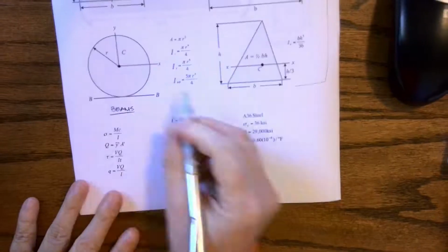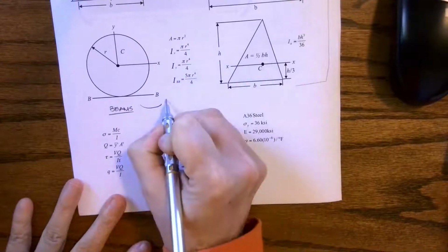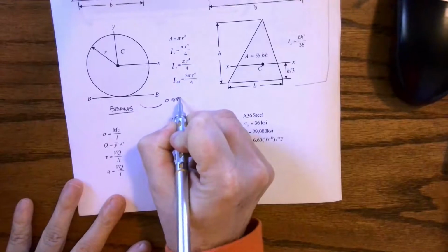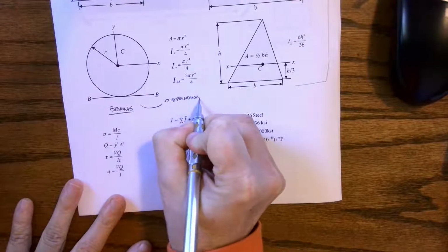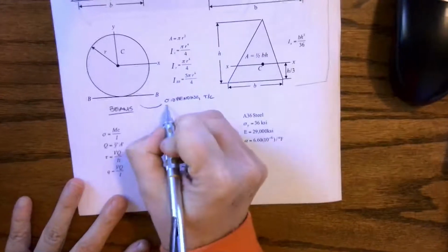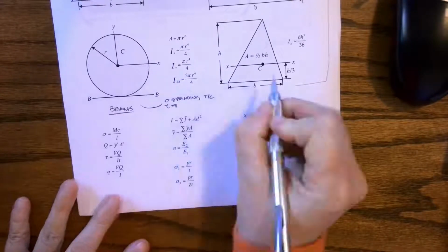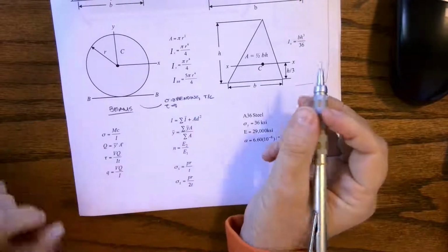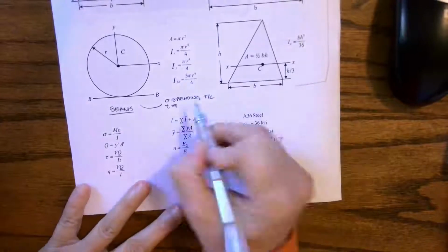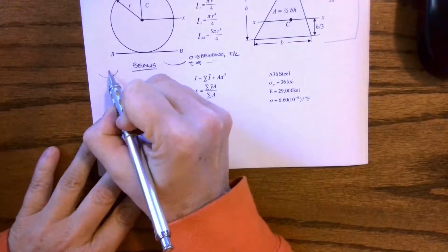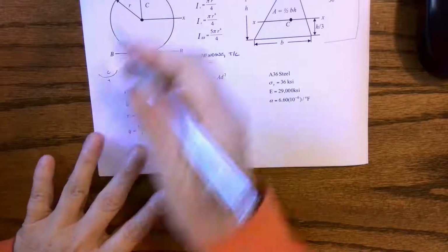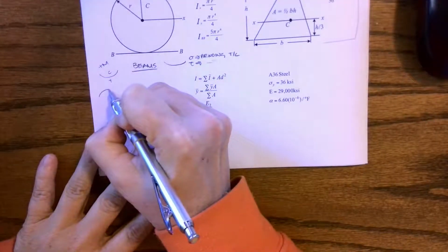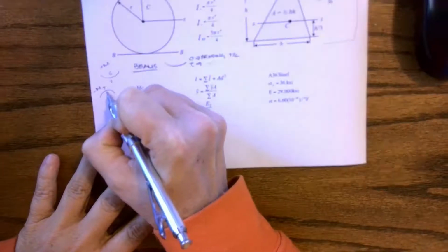So we have beams. And when we have a beam, we're going to have a normal stress from bending, and that's tension and compression. And shear stress, which we look at longitudinally, also technically comes from bending, and we don't really look at direction. As we have deformation, we might have compression on top and tension on bottom, and this would be from a positive moment. With a negative moment, we have tension on top and compression on bottom.